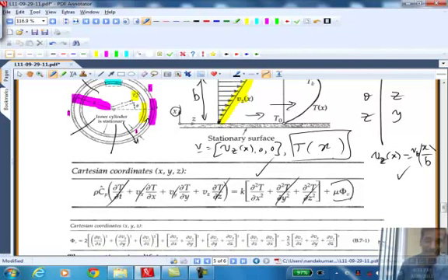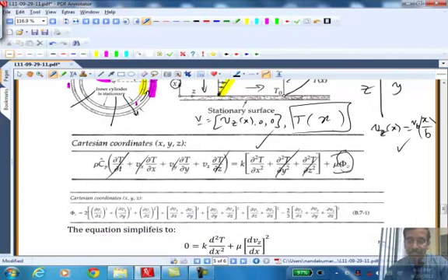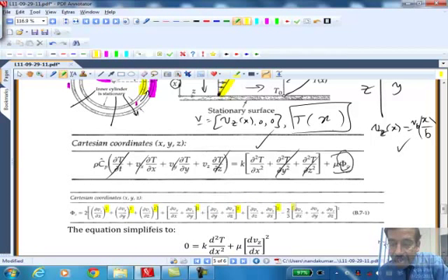And what you need to do is that expression for the viscous dissipation is a pretty long, messy expression. But we saw already that it is a positive definite function, meaning it's always a source term. It can never be negative. And if you notice, all of them will have a square in it. If you're squaring any number, it's going to be positive, right? Any number inside negative is going to become positive. So phi v will always be greater than 0.